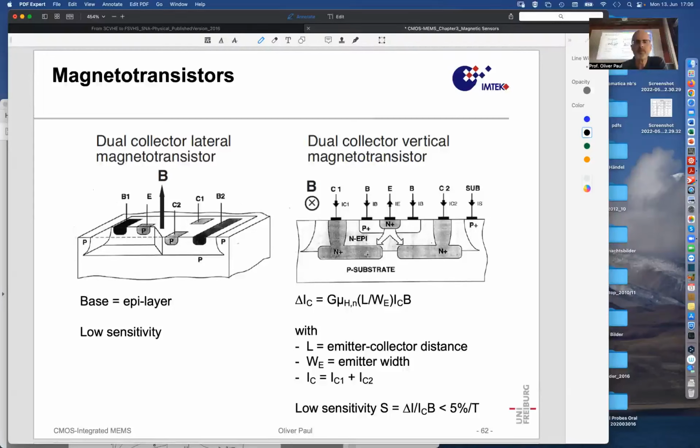So what was the idea behind? When you have a magnetic field parallel to the chip surface, therefore lying in the plane of the chip, it will kind of direct the charge carriers from one side more to the other. Yeah, and so it looks a bit like a split drain current device. So the question was, is that really the fact?